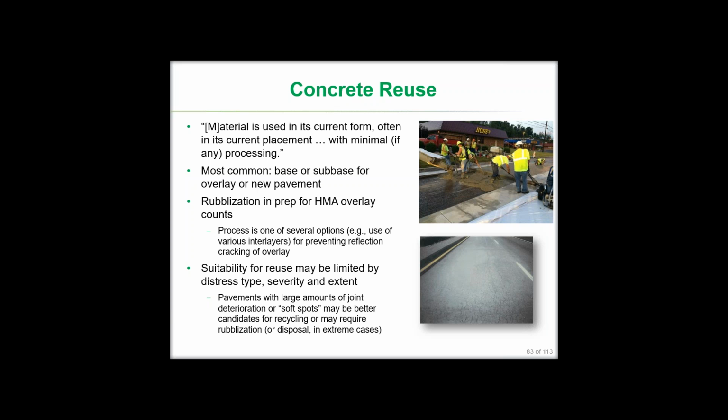So rubbleization and then using the pavement in place as a base for an asphalt pavement still counts as concrete reuse. And the suitability of any given concrete pavement for reuse obviously is limited by the types of distresses that are present and their severity and extent. The photo off on the right here shows a fairly, let's call it moderately alkali-silica reactive pavement that, depending upon the rate of deterioration, may or may not be suitable for reuse in place as a base layer. Might call that a self-rubbleizing pavement, I guess.